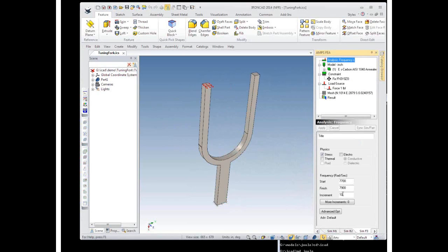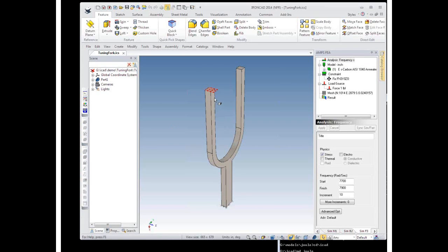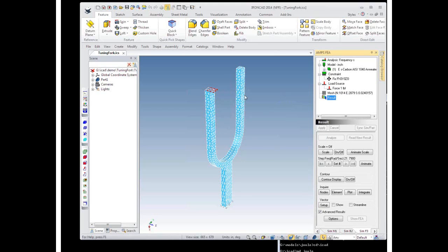The third type of a dynamic motion is called a frequency domain. So let's say you're vibrating this at the tuning fork at the loading, which is basically nothing but 1 pound. Okay, so what's going to happen is that if you happen to operate this load at the natural frequency of the tuning fork, it's going to resonate, and the deformation is getting larger and larger. And if you do not prevent it from happening, it will eventually collapse the system.